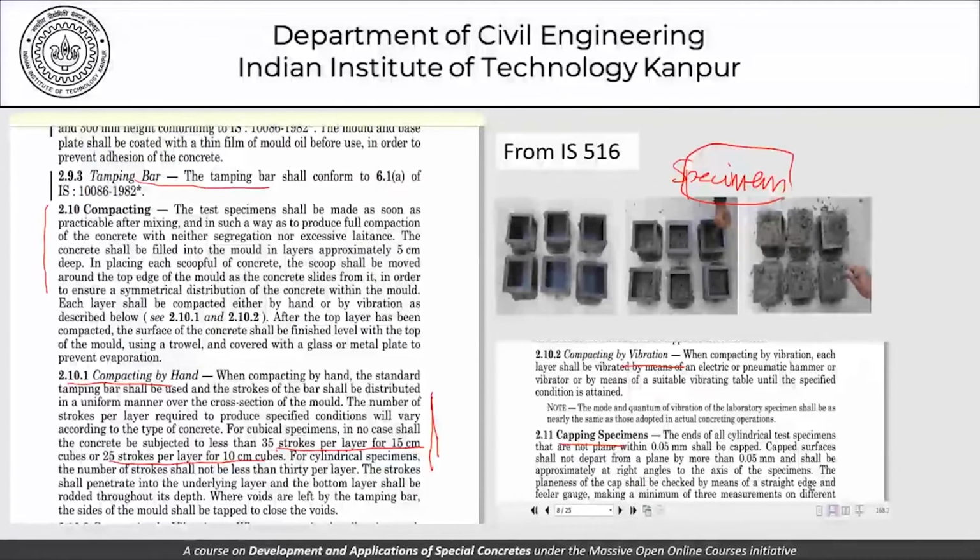for normal conditions. One thing you should remember always, that the concrete that we are trying to test, the concrete proportions that we're trying to determine, and finally the concrete that we test for strength or slump or whatever it is, the idea is that the concrete should be suitable and it should serve the purpose in a given structure. So all these cubes that we take are, of course, not a true representation of the strength that will develop in concrete in an actual structure. So that is something which is known to us, and that's why we say that this is the cube that is being used for quality control of concrete.